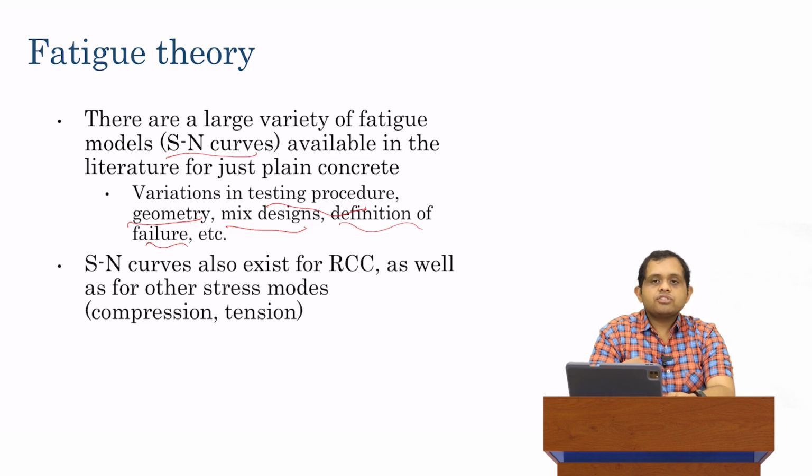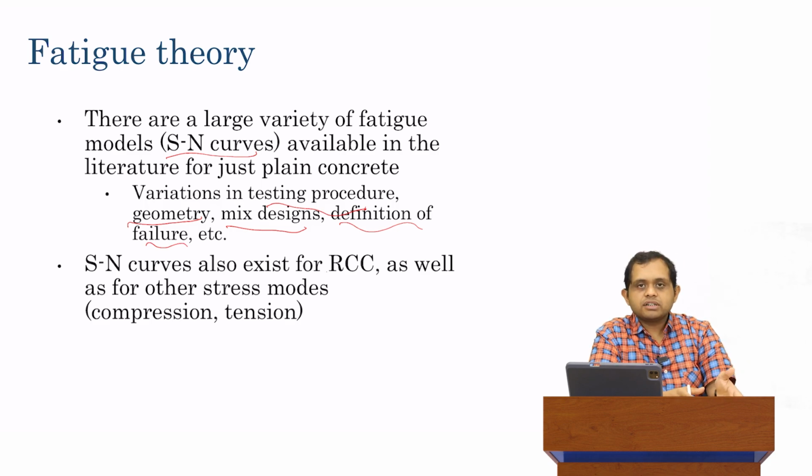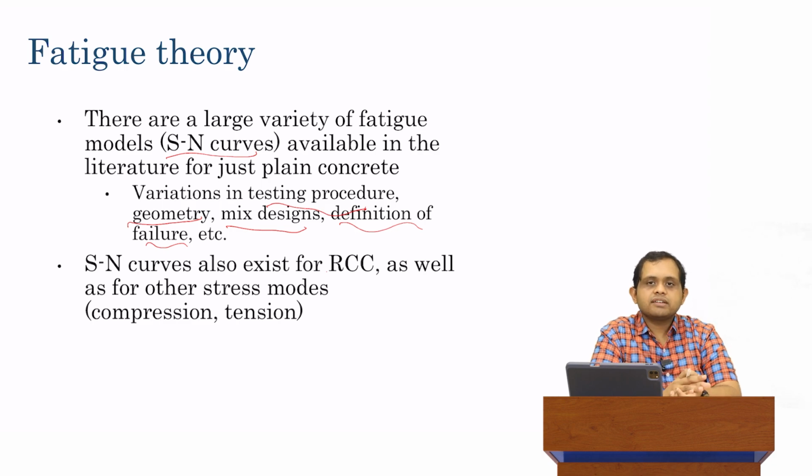Definition of failure also changes. If your definition of failure is based on the reduction in modulus, you'll get some SN curve. If it's based on observing a macro crack, depending on how good the eyesight of the experimenter is, you can have different SN curves. So there are a large number of these models. Furthermore, in today's lecture and basically for this class, all we're studying is the SN curves for PCC, that's plain concrete.